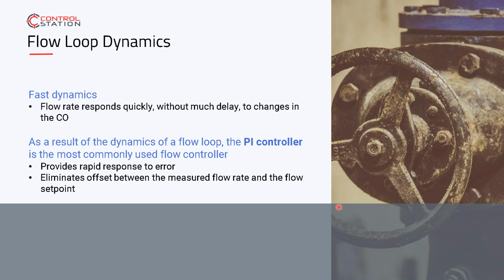If the valve is limited by mechanical issues, which Damien will elaborate on in further slides, you're going to hinder your ability to control flow at set point, which can cause all kinds of problems, which we've already discussed: wasted energy, decrease in process yield, decrease in process quality. So in flow loops, you need a valve that's going to react quickly to the desired output.